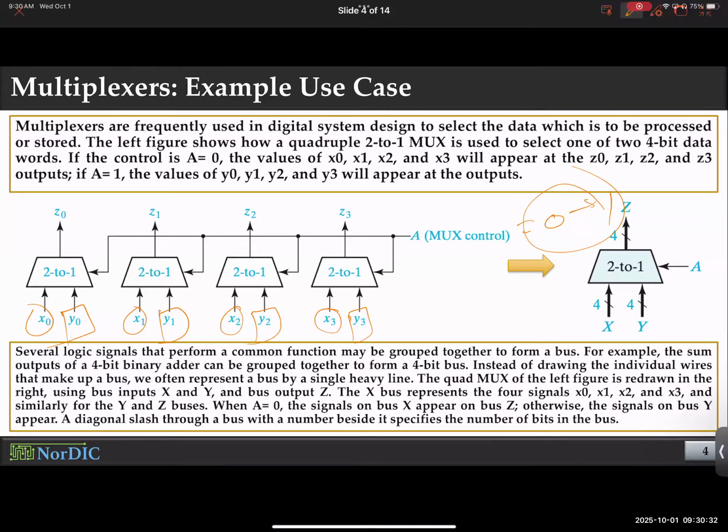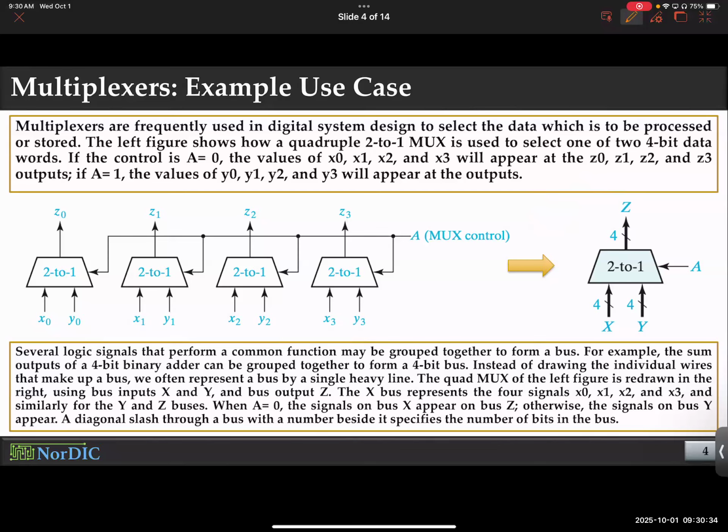First of all. Number 2, imagine if I have a hardware diagram, especially, for example, you're trying to draw a diagram for a Core i7 processor. It will make the engineers crazy to keep tracking all those hardware components if you go down to that level of granularity. So we try to abstract it out to a higher level and reduce the number of symbols we want to use. And this concept of bus helps us. And you can read this that I've written here at home. But long story short, when you have a number of bits that basically represent the same thing, it's a repetitive circuit. You could represent that in the form of a bus.